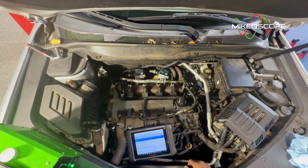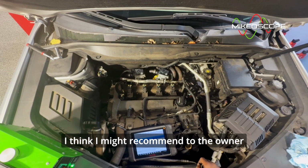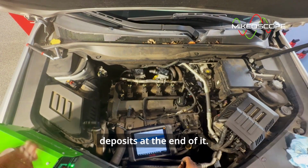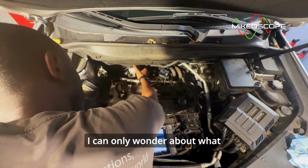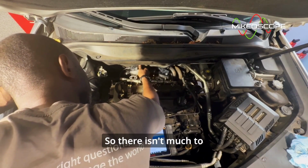So based on what I found, I certainly think my problem is the pump at this time. But with how that is looking, I think I might recommend to the owner to change this as well because it's got too much deposits at the end of it. And I can only wonder about what it looks like on the inside. This is not serviceable, so there isn't much to do with it right now.